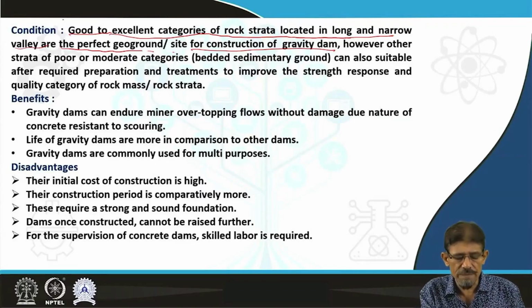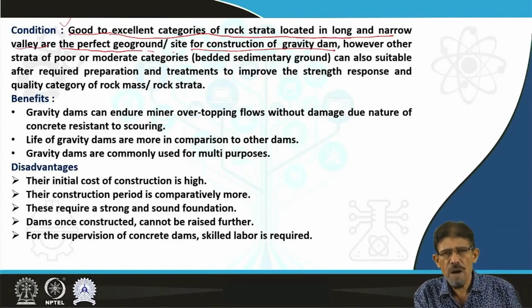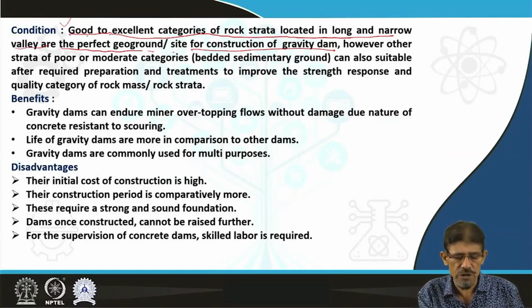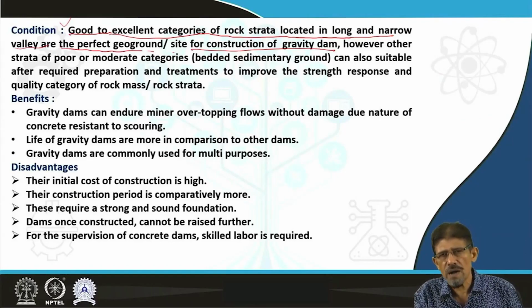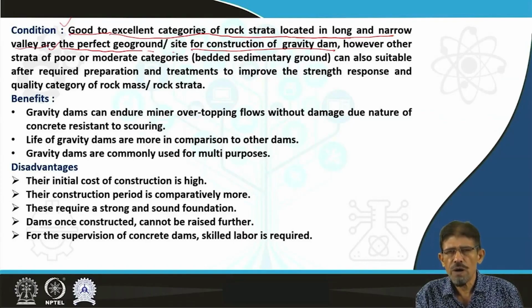In that system, this type of dam foundation requires good to excellent category of rock mass located in a long and narrow valley, because this type of ground is able to bear the load of a heavy concrete structure.